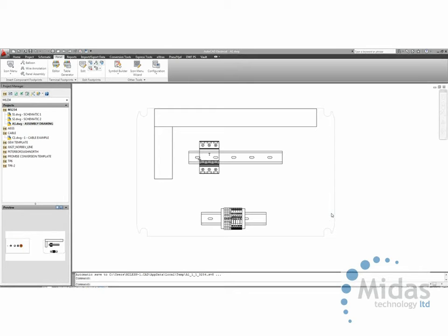Moreover, after you've done a design, you can produce an Excel spreadsheet, as an example, modify the component tags, and then bring the component tags back into AutoCAD Electrical. Why is that useful? Well, your tags might be defined by the client, linking to maybe loop diagram tags that have been defined within P&ID drawings, as an example.